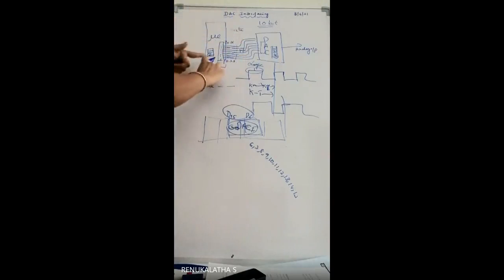We take a microcontroller which has 2 ports here, port 0 and port 1. For the time being, we are taking port 0 for all purposes of interfacing. Here you are usually taking P0.16 to P0.23, 8 data lines, 8 pins. We place suitable data using a suitable register. It may be the IO pin register. We place valid data into the IO pin register, which in turn places the data onto port 0.